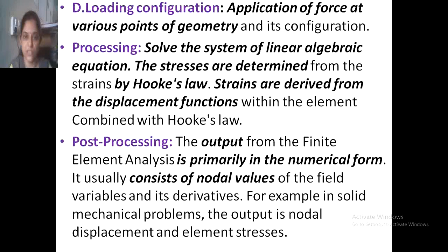In processing, we solve the system of linear algebraic equations. The stresses are determined from the strain by Hooke's law. Strains are derived from the displacement functions within the element combined with Hooke's law.